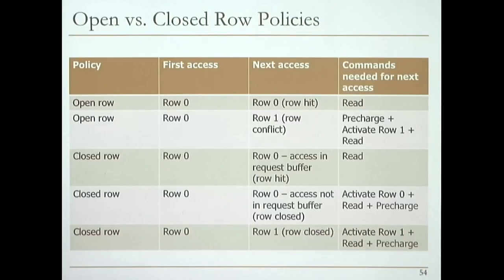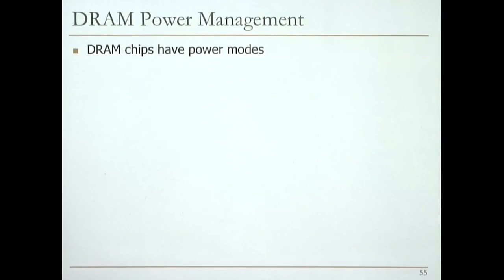Because if your row is open, at least you can design your memory controller to look at the request buffer to see if there are other requests to the same row. If there are other requests, then you don't close it immediately. OK, let me see what I have over here, because I think I can cover this, and then we can go into something else.